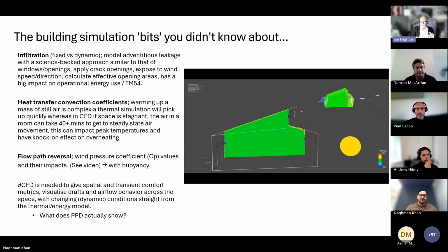But in the real world, coming on to the third point, you've got different set points, and you end up with simultaneous heating and cooling. You just don't see that in the perfection of a dynamic simulation model, because we're told to hold a very clear set point. Yet in real buildings, you've got somebody on one side of the office turning it up, and one person on the other side turning it down. One's too hot, one's too cold, and you get huge amounts of simultaneous heating and cooling. So in terms of the performance gap, well, the performance gap doesn't exist. If you put all of the stuff that the real world is doing into your DSM, you get back to within 5-10% maximum.